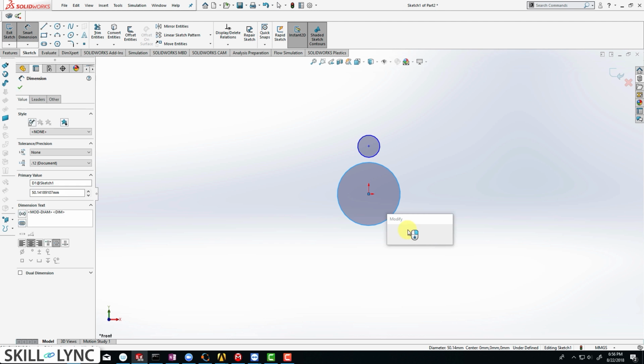Let's click OK. Finally, we basically do the same thing for the top circle, right? And make sure that you do it on both the sides. Only then your cam is going to turn out symmetrical. This is an important step, so make sure that you follow this carefully. Just click on OK when you're done. So now what we need to do is just trim unwanted entities. Let's make sure that power trim is selected. And then let's just drag it out and delete unwanted sketches.